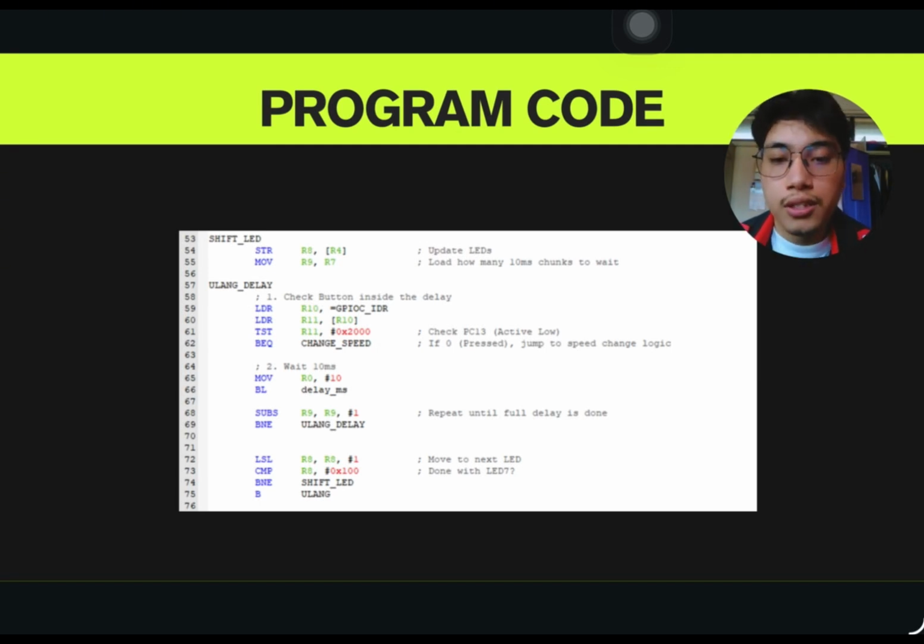This is essentially how the LED shifts from one to the other. For the first LED, the value is 0x00000001. Then we apply the logical shift left to shift the value, and it will store the value into R8, which is now 0x00000010.